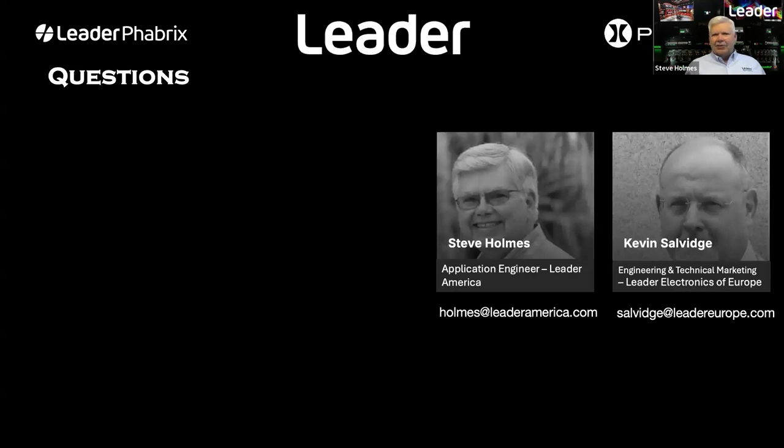Sandy, another question here. Is there a way to prevent double LUTs by mistake? There is a way. As I said, we have the ability to burn in onto the picture display on the waveform monitor itself an indicator saying that the LUT is on. It will say something like NBC Universal or BBC 9C LUT. It's on the screen, though it is not burnt into the confidence monitor output.